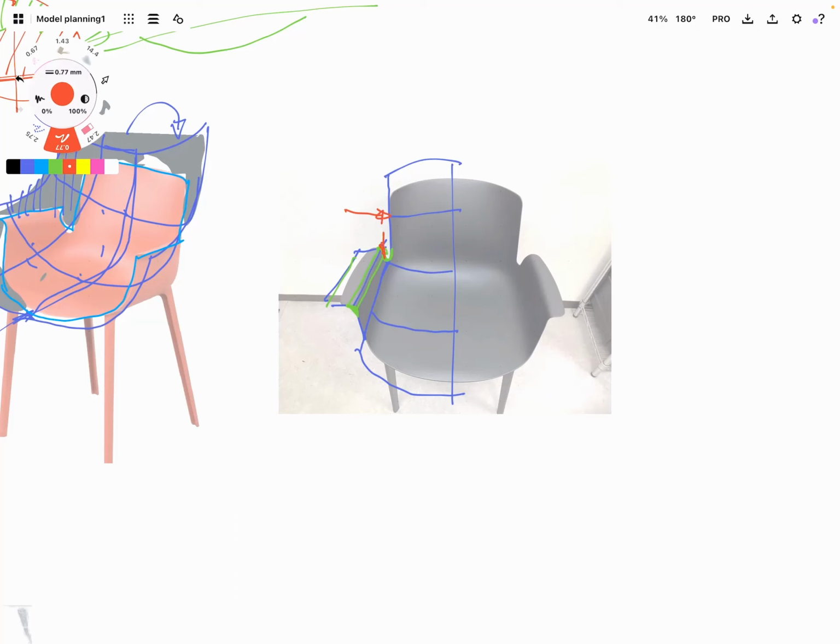so you can deviate. The reason they've got this cut here is for seat performance, so this can go forward and back, and the arm can move independently. So if this was joined here, there's a bit of an issue with chairs. When you lean back here, the arms want to go inwards. So that's why they've got this cut.